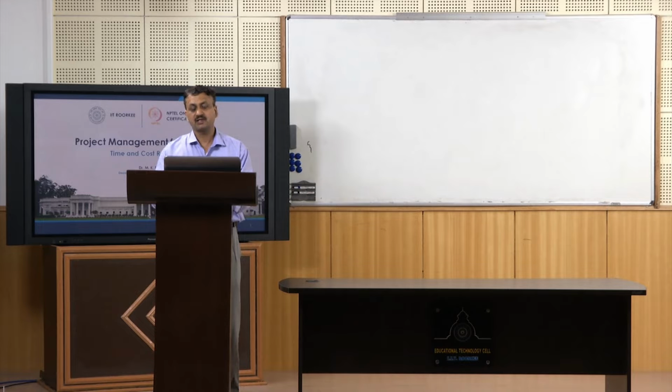So if you look at, let's say there are 3 activities, right? Let's say activity A, B and C. So B is the current activity, A is the preceding activity and C is the succeeding activity. So the maximum time available for delaying activity B is nothing but that would be called total float, right?